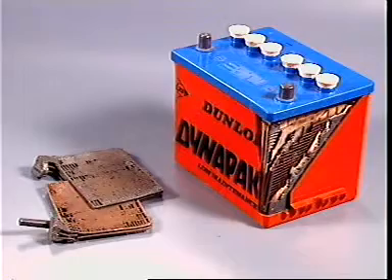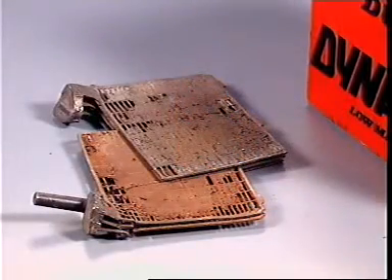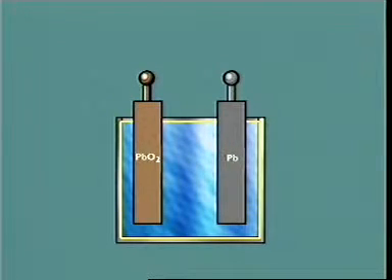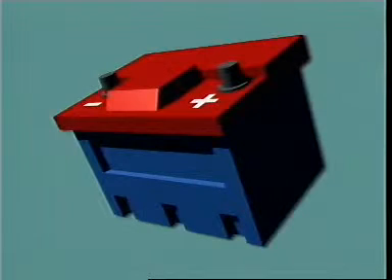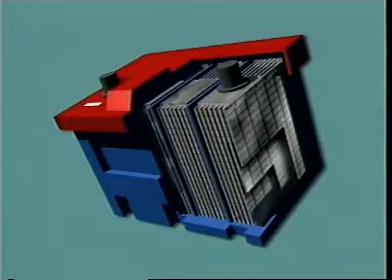In automotive use, the usual main storage device is the wet cell of a lead-acid battery. It has two plates of dissimilar materials immersed in an electrolyte, a solution that conducts electricity by using ions. The accepted or nominal voltage of a cell does not depend on the size of the cell. However, current capacity does. The surface area of the plates in a cell determines its current capacity.